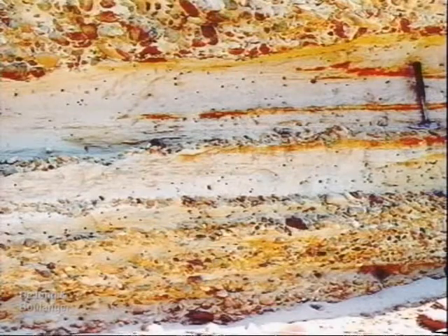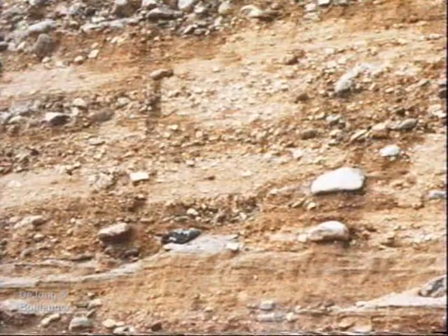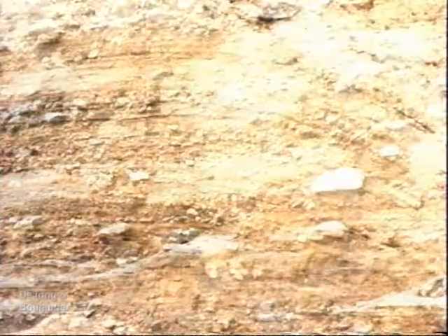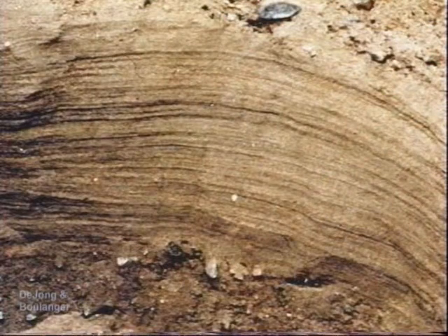These views of alluvial sand and gravel deposits are shown to emphasize that even relatively homogeneous deposits can have complex interlayering and heterogeneity on a local scale. An appreciation of the inherent complexity of geological deposits is needed for planning or interpreting subsurface explorations.